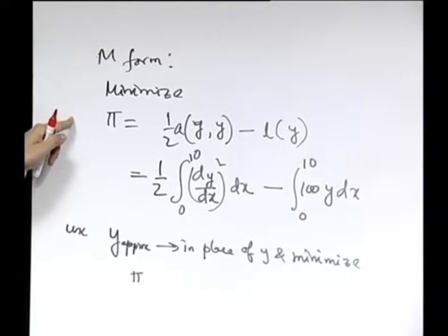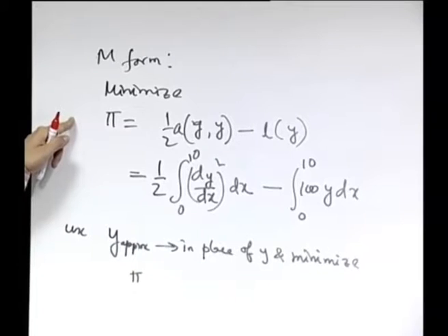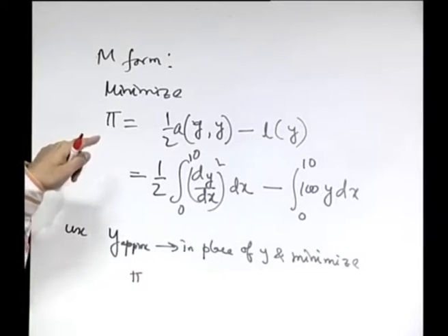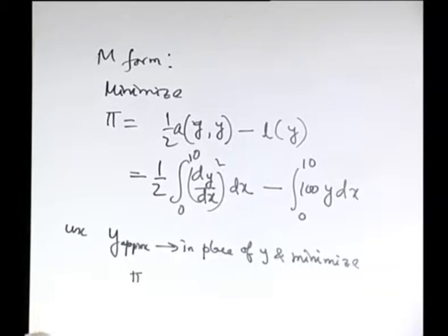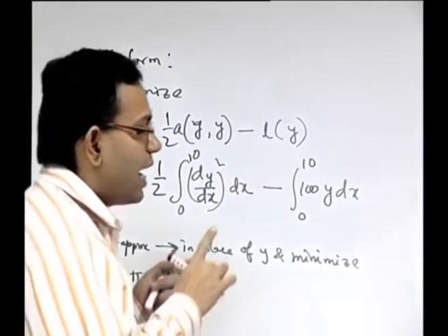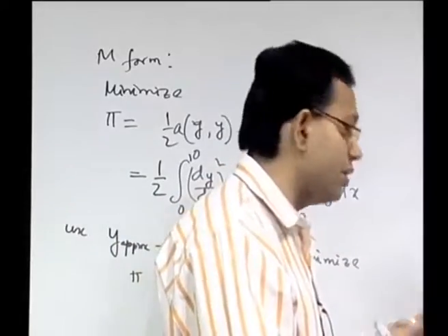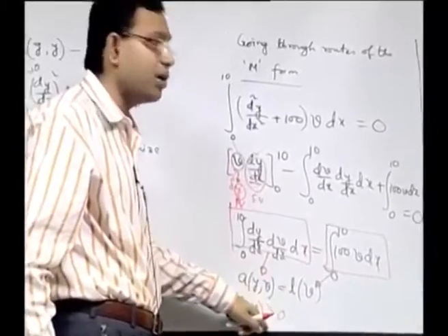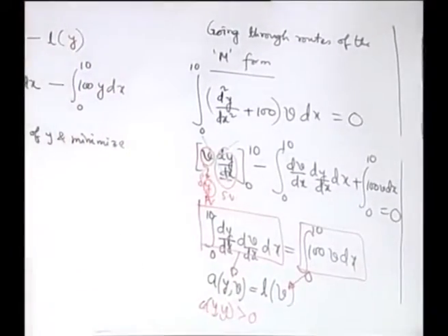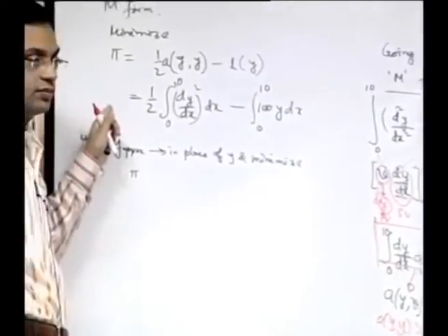So, here also you have a trial function, but what is the difference with other methods like Galerkin's method? You do not have any weighting function here, just a trial function. But you had to pay a price, or rather a requirement had to be satisfied, that it is a positive definite operator. If it were not a positive definite operator, you could not have come to this form.